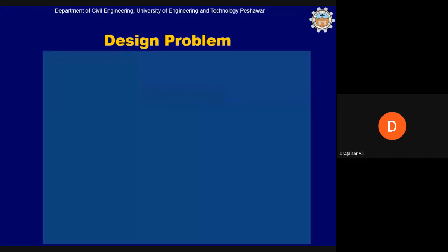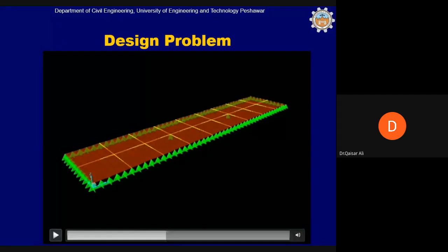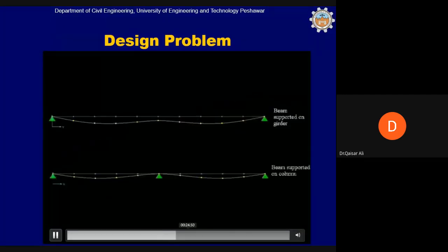You can see in the deflected shape. So for this reason, we have chosen a 36-inch deep girder. If we further decrease the depth of this girder, then this part, which is a curvature up, means that negative bending moment is developed here, and some kind of resistance is offered by the girder to the beam in order to minimize the deflection of the beam at this point. If this is not done, then this whole point will come down, and the deflected shape will be like this.